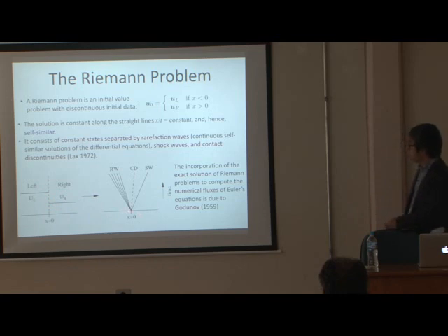If you take this value, we say this is the Riemann solution at this point. We have propagation of the contact discontinuity, propagation of the shock wave in the right direction, and propagation of the rarefaction wave in the left direction. So this kind of information happens every time, making some discontinuous structure.